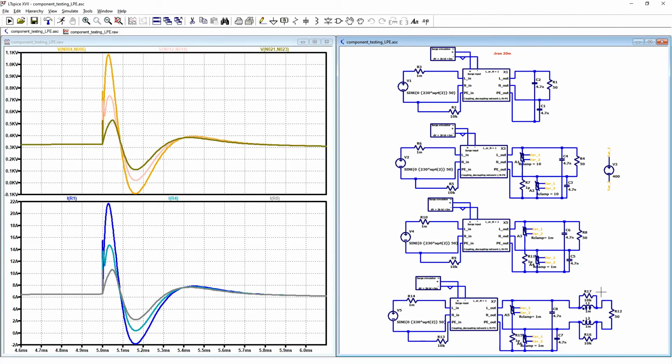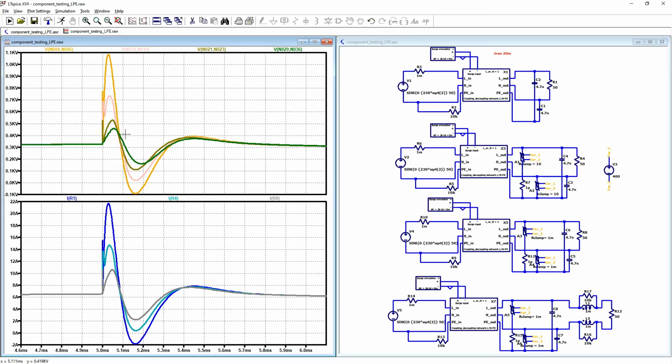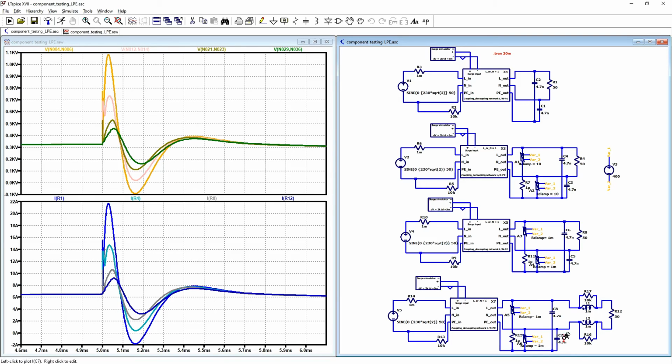higher than 10 amperes. And what will happen? We have our common mode in our filter. So first component with varistors, maybe a fuse there, CY capacitors, and a common mode choke. This will be a filter with additional varistor for transient protection. And let's see what the voltage is now. Voltage is even lower than before, and the current is also smaller. So the total energy is minimum when we have varistors, capacitors, and the common mode choke.